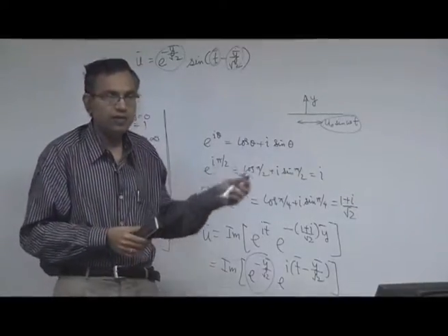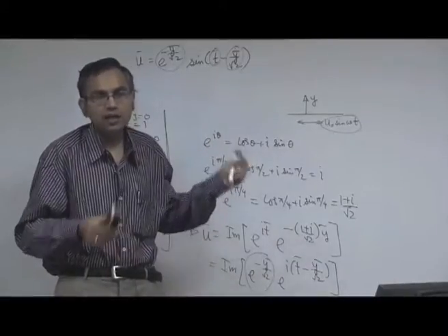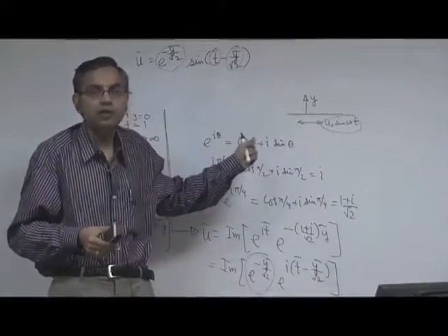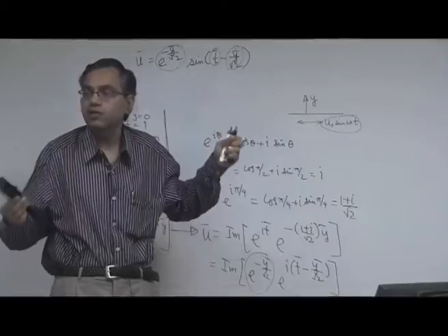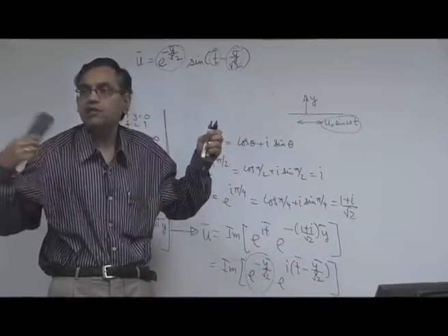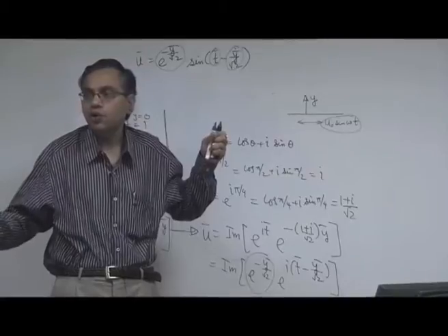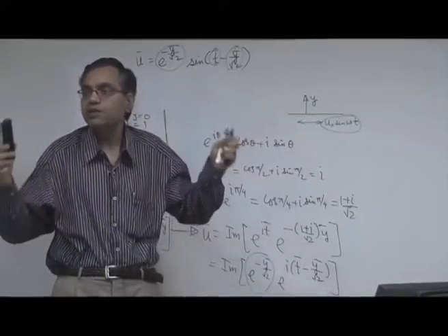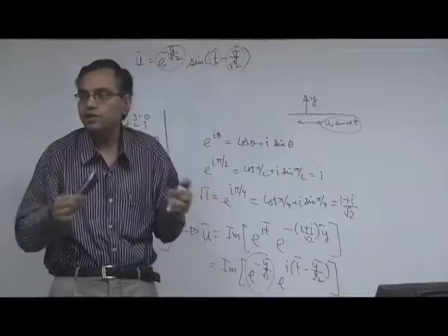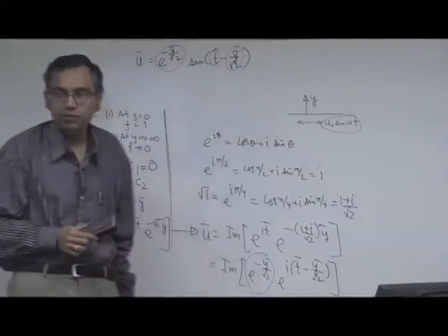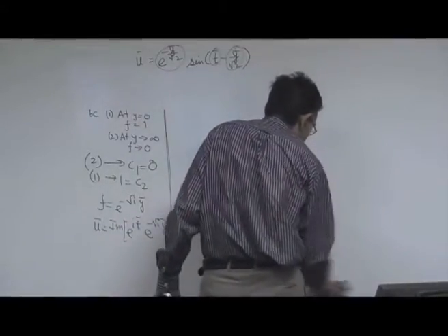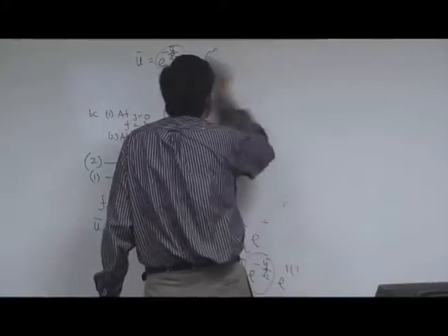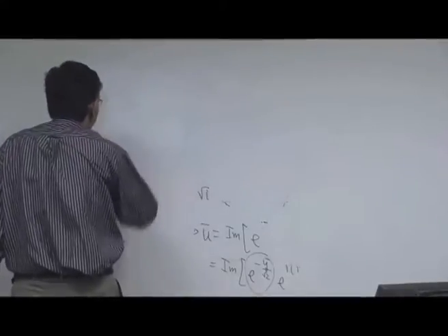So, the motivation of studying the Stokes second problem in the context of microfluidics is not that it is really a microfluidics problem, but it gives a basis which is a case of an unbounded flow, so that we can consider the case of a confinement or a bounded flow with this particular case to see what is the explicit role of confinement towards driving the solution for the velocity profile. So, with that motivation we will consider the next problem.